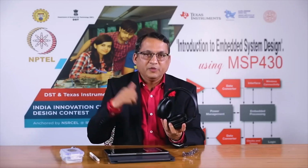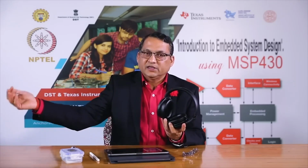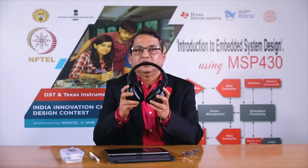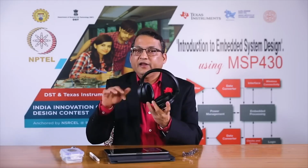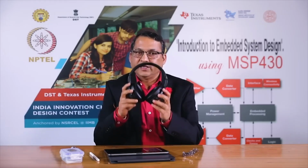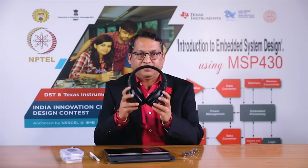This noise cancelling headphone samples that sound, produces an anti-phase version of that sound, and mixes it into the speakers in these cups, so that you are actually hearing three sounds: the music that you are playing, the external sound that is leaking through the cups and entering your ears, and the anti-phase version that this headphone is creating. That anti-phase version cancels the noise which is coming from outside, and you hear only the music that you are playing. And so, it gives a great example of an embedded system.